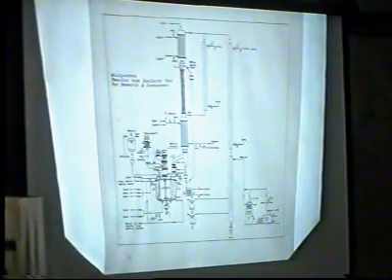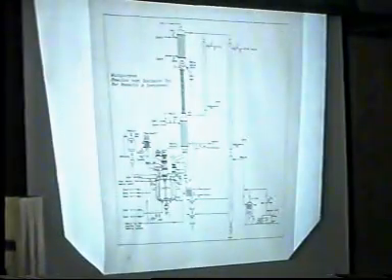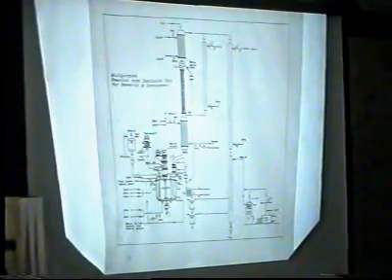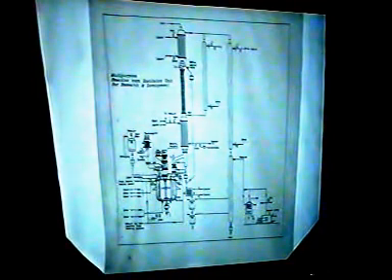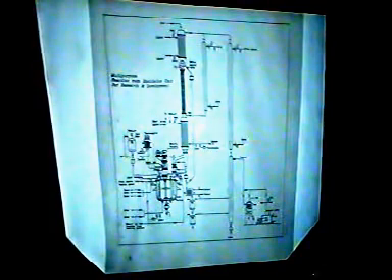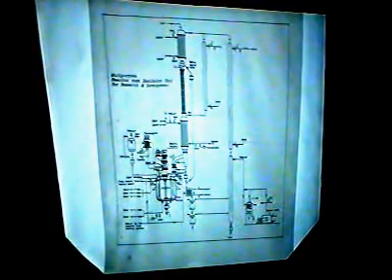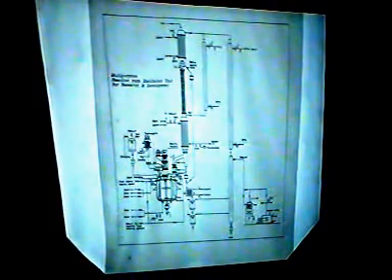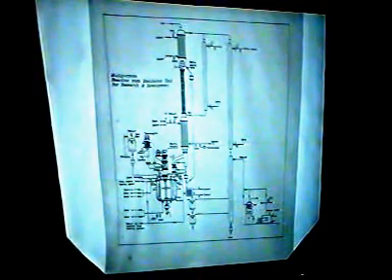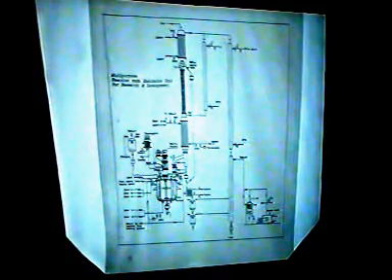A glass visor is provided between the dosing tank and the reactor to see and adjust the rate of addition manually. See, there is a glass visor here which is provided to see at what rate we are adding a reactant inside. An extra nozzle on the top dish facilitates addition of solids. There is an extra nozzle here from where we can add the solids inside the reactor. A vapor nozzle with an isolating valve is provided to facilitate conducting hydrogenations or oxidations in the same reactor.